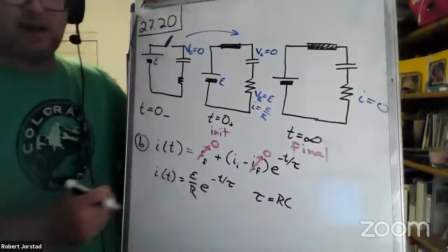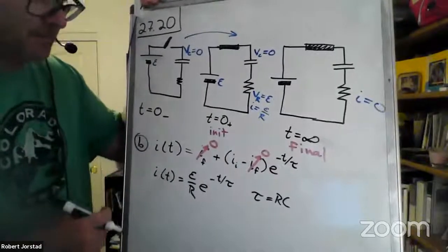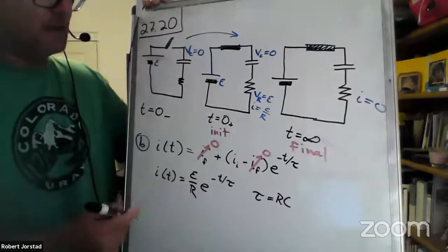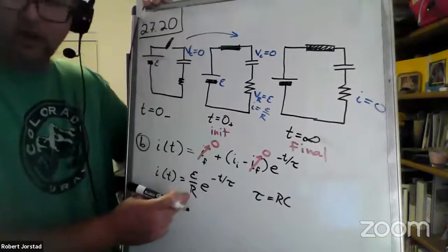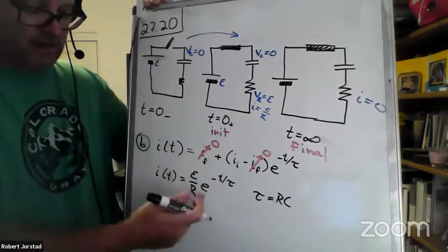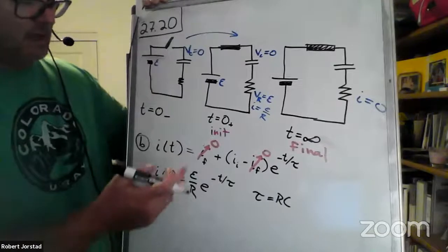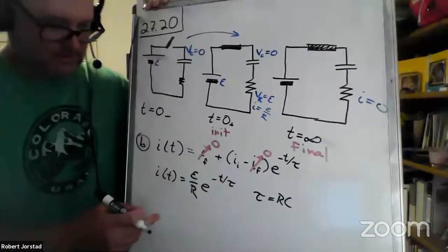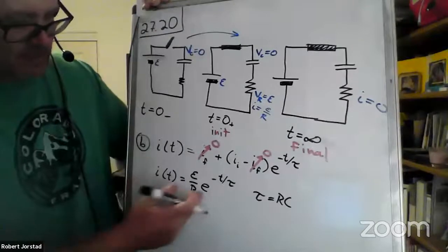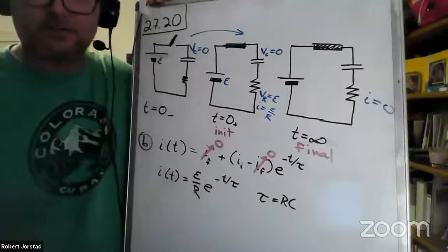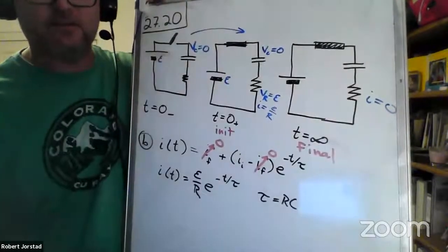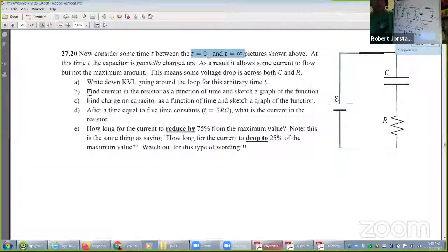We'll discuss more if we have more complicated circuits. Sometimes tau gets weird. We should cover that within an hour or so. All right, R and C are knowns, so tau would be known. E and R are knowns. And e is just the number, 2.71828, etc. So we know that number, and we now know the current as a function of time. Let's check. I believe we have now answered part B: find current as a function of time. Oh, and graph it. Okay.